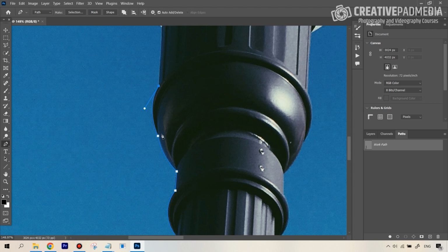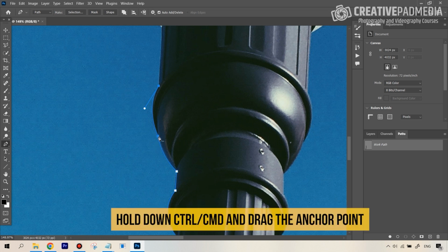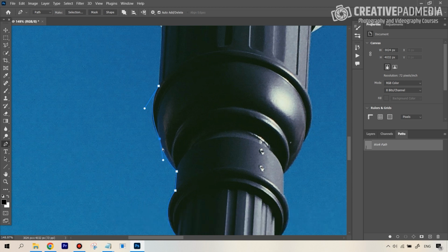Okay, by the way, before I just undo, you still have some control over things, because what you can always do is, suppose I felt now I wanted to change this curve a bit, you can hold down Control or Command, so not Alt Option this time, and then you can move this point slightly like this. But can you see we only still have that one bar, its sibling has gone because we deleted the sibling, so we don't have that much control on this. But you can still move it by holding down Control or Command on the anchor point. You can make some changes.